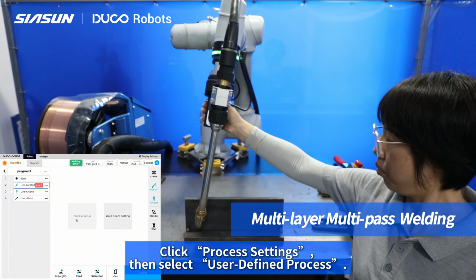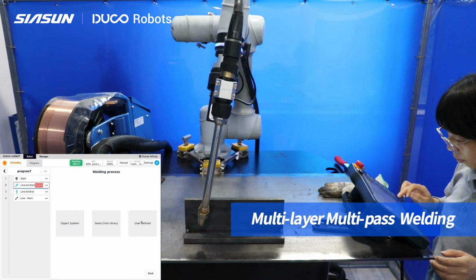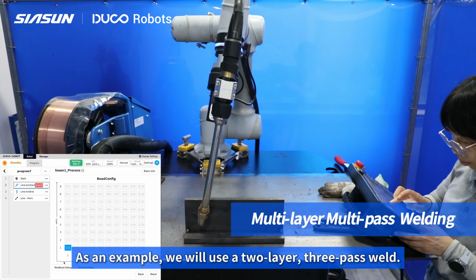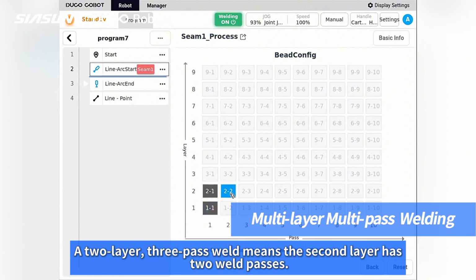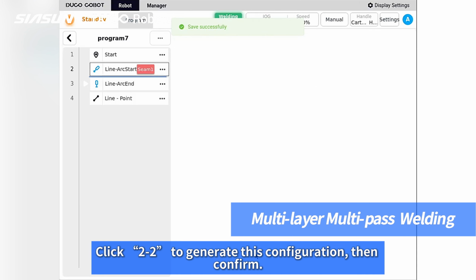Click Process Settings, then select User-Defined Process. As an example, we will use a 2-layer, 3-pass weld. First, click Bead Editing. The horizontal axis represents the pass, and the vertical axis represents the layer. A 2-layer, 3-pass weld means the second layer has two weld passes. Click 2 to generate this configuration, then confirm.